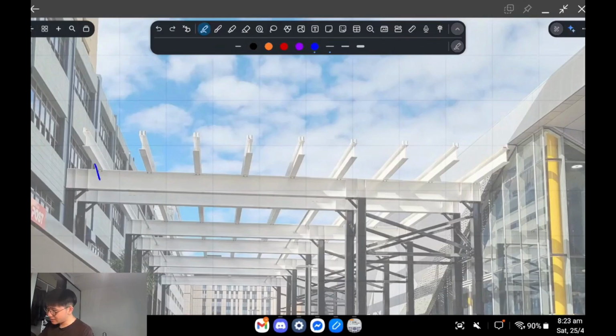What typically happens is you see these things if you've looked up in a warehouse, right? So say you go bouldering or something, you might have seen these little diagonal thingies, struts, I guess you can call them. Braces, I guess, is even a better word. It's called fly bracing. So fly bracing, usually it's on both sides, so it'd be on the other side of this beam too. Fly bracing is used to restrain the bottom flange of your beam. So it's got a flexural restraint as well. Okay, so anyway, that's that.